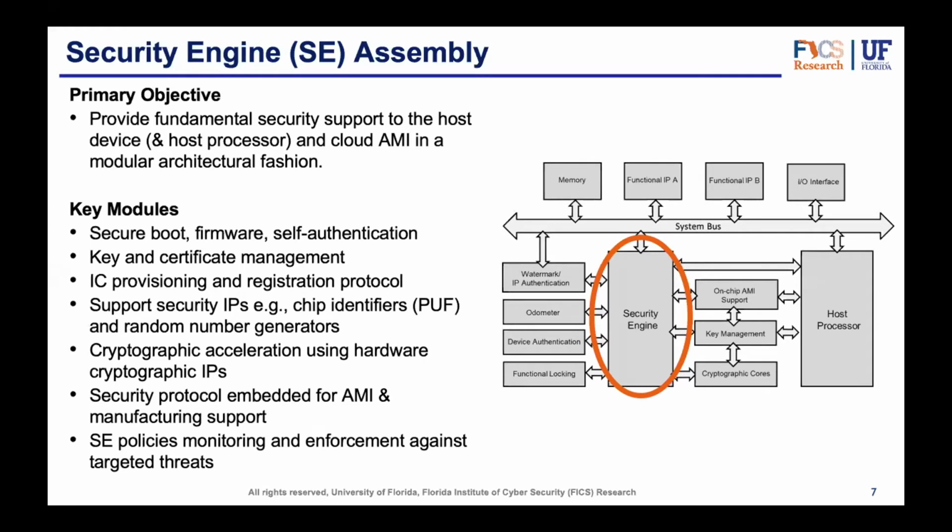It provides secure boot, self-authentication, key generation, certificate management, and IC provisioning at different stages, mainly starting from the fab floor, and supports security IPs, getting access to the security IPs, etc. Another important functionality is communicating through on-chip AMI and host processor to cloud AMI. And the last one is to not only monitor security properties within the device, but also enforce security properties.